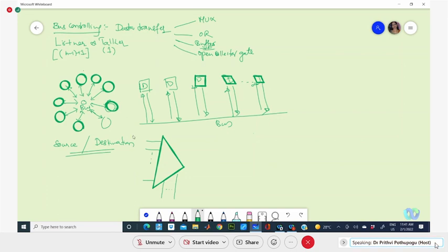So each device, or each destination, a device which is trying to send the data or receive the data, device 1, 2 and so on to device n, we are taking. This becomes the selection line, where it depends on how many destinations, or devices, you are getting connected. So an n is to 1 mux will be taken, and this is your bus.